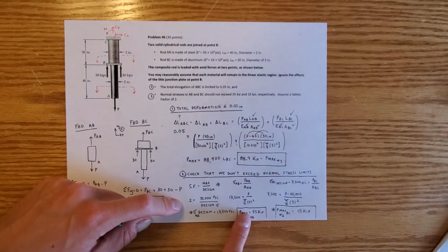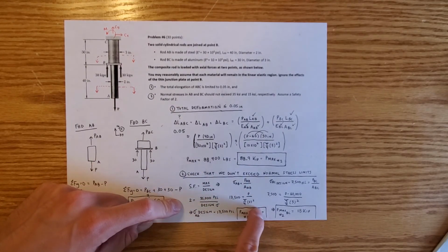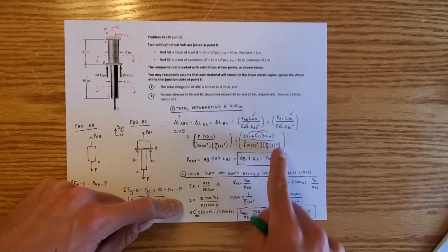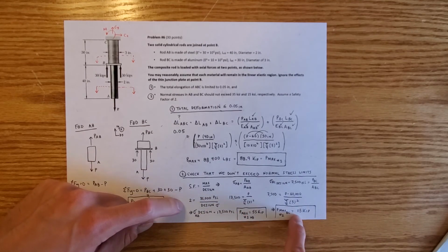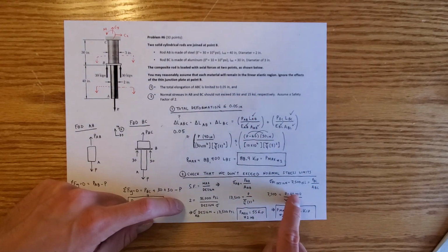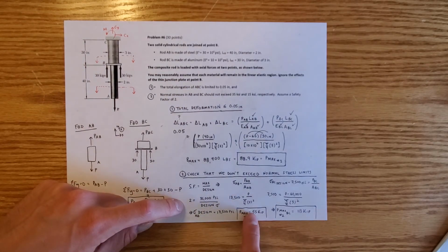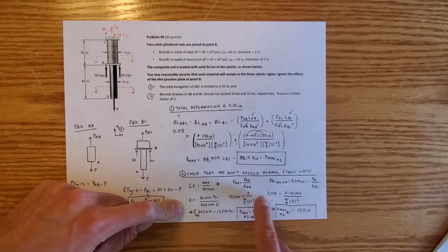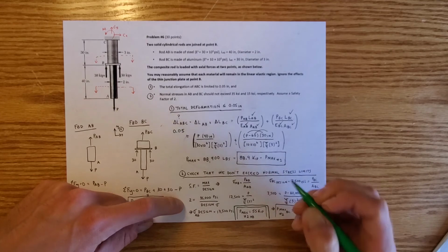So right now, 55 is less than 88.9. So if we applied 70 kips, sure, we would have satisfied this condition, but we would have failed under this condition right here. So right now, 55 is our limiting factor. If we look, PBC has a maximum value of 113 kips allowable before we get 15 KSI in that rod right there. So as a result, what this means is that 55 kips is the lowest possible force of the whole thing that satisfies all conditions. So this is our true final answer right there.